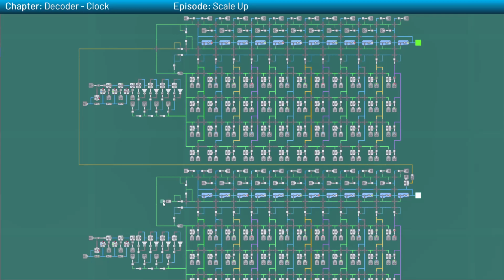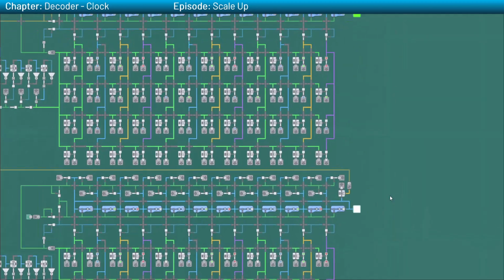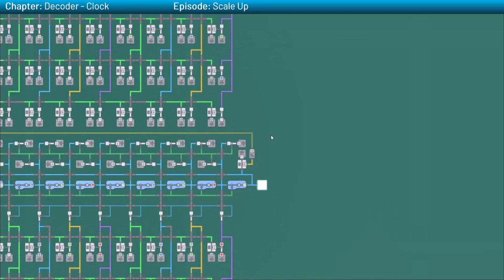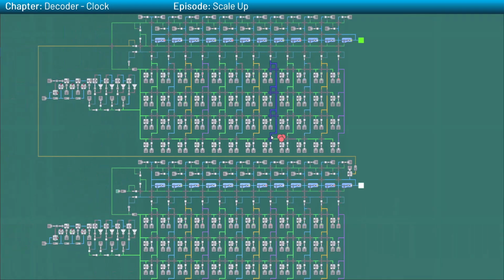And that is not what we want either, because we want this machine to switch if this one switches back to its first value, which is red. So we cannot use the rising edge detector. We need the other one, the falling edge detector. The falling edge detector means when this switches back from 1 to 0, then we are going to emit a pulse. So let's try it again.